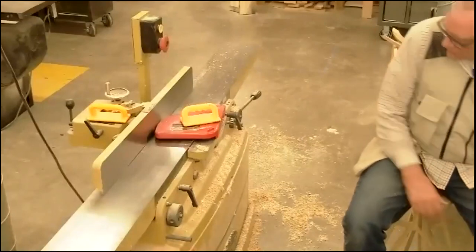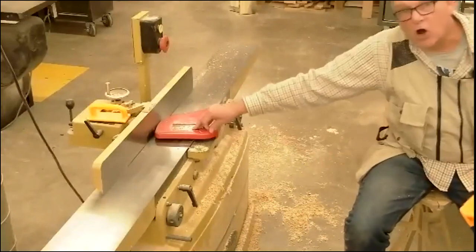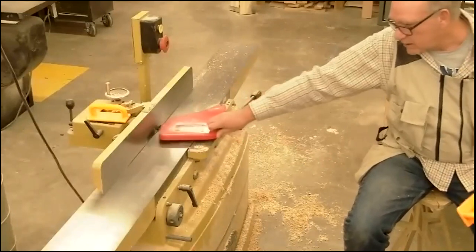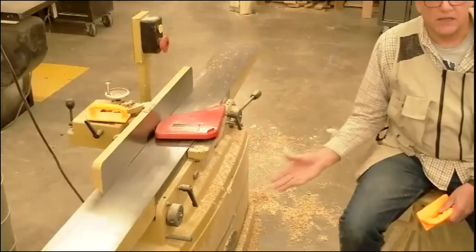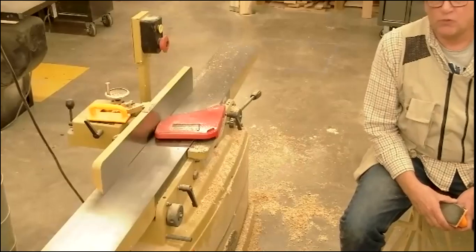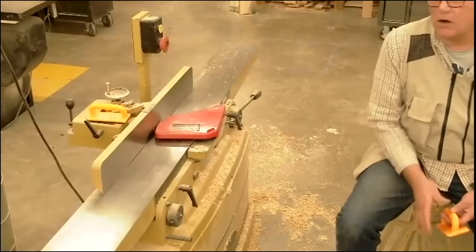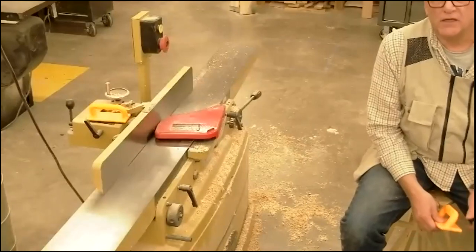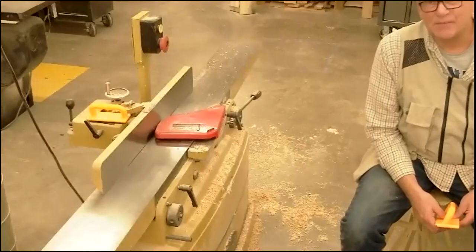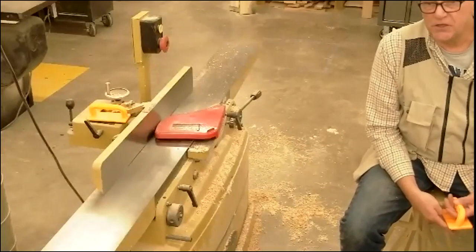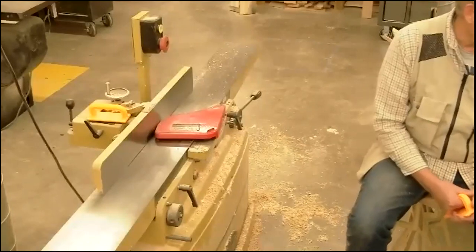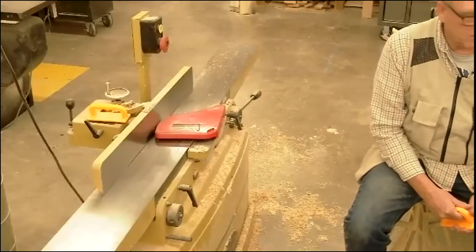Last but not least, this red thing right here, this is the guard. Never, ever, ever move the guard out of the way while you're running the machine, okay? That goes with any guard in this shop. We do not move, alter, disable, remove, or bypass any guard on any machine for any reason whatsoever. If I ever see a student moving a guard out of the way or bypassing a guard or disabling a guard or not using it the way it's supposed to be used, you're gone. You will never step foot out here again. That's a huge, huge safety infraction. So just don't do it. You could get very, very badly hurt.